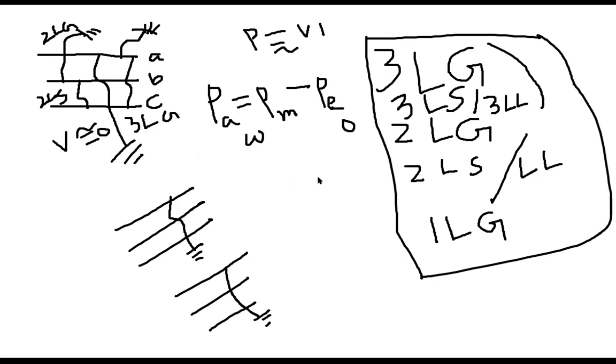In the last class we looked at the definition of balanced and unbalanced three-phase systems, whether delta or Y connection. Even though it is a fault, whether it is 3LG or 3LS, because it involves all three phases, they will have equal impact. So with a fault, current will increase and voltage will go down, but they will still maintain the proper 120 degrees. That's why it is called the balanced fault, because all three phases have been affected equally. So there will not be any change in the phase difference. Got it?